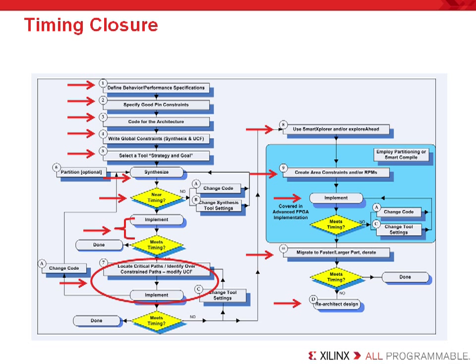Next, sometimes to change the tool settings, designers will use the Smart Explorer or Explore Ahead utilities. Explore Ahead is specifically a utility that's included with our PlanAhead software, but both have similar functionality. They're basically high-level ways of running the implementation and synthesis process with different options to see if we can find a combination that will generate faster results than you've already gotten. So it'll basically generate different implementation results. It's worth trying, but the caveat here is that you run the tools multiple times, so you may end up locking your machine for quite a while. So this is why it's further down. Even though it's easy to do, it's further down the list. We don't like to tell customers to go try this and then call us back a few days later and say it didn't work.